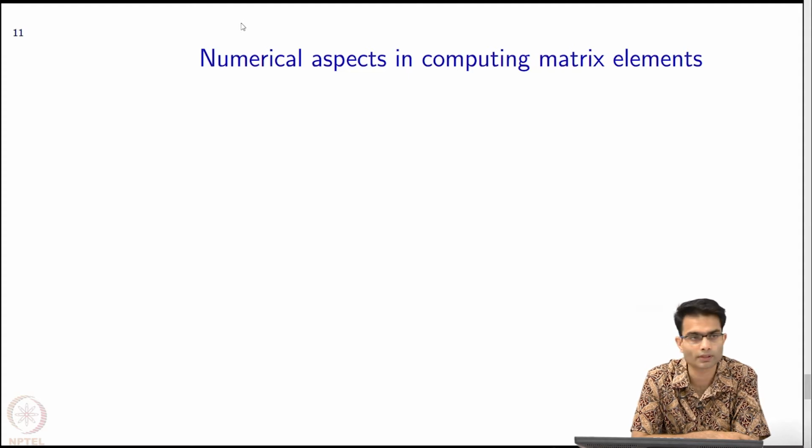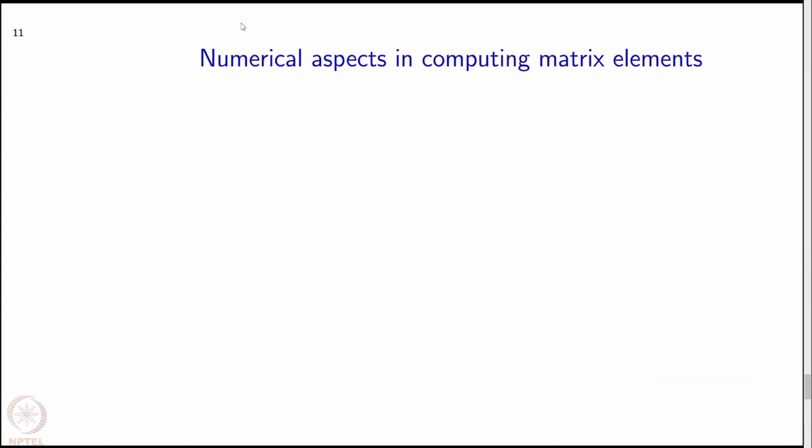Today we will look at the final aspect of the 2D FEM, edge based FEM, where we look at some of the numerical aspects that go into calculating the matrix elements. So far we did not talk at all about how we will calculate the matrix elements, right.